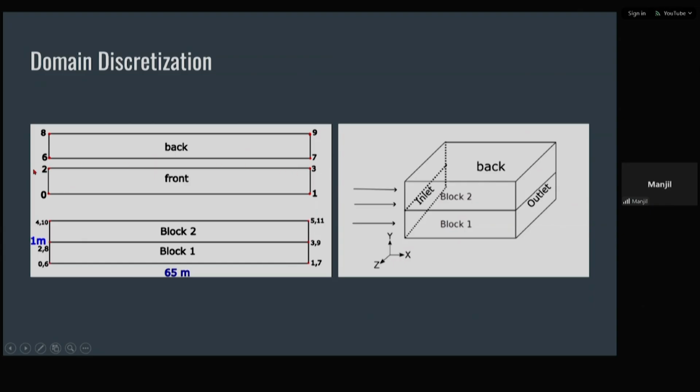After I have named the front face using 0, 1, 2, 3, I also need to assign the x, y, z values of these coordinates. Actually, this is just naming of the coordinates. I refer to this as coordinate 0, this as coordinate 1, but they have their own x, y, and z points. In order to make block 1, we need 8 coordinates: the front 4 coordinates, and the back face at the back, which requires 4 coordinates. After we join the front and back faces, we will be able to create block 1.